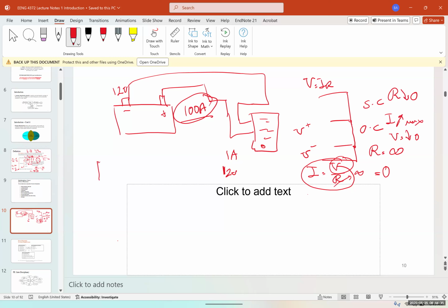Usually they are a tin wire, like something like this. And when they heat up, it's just gonna burn out. Some of them, in cars especially, are single use. In your home, you have a breaker that you can just reset, but in a car, and even those breakers, if you put too much current in it, it's gonna blow.